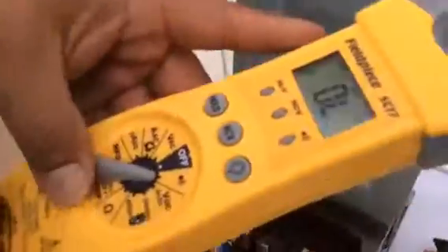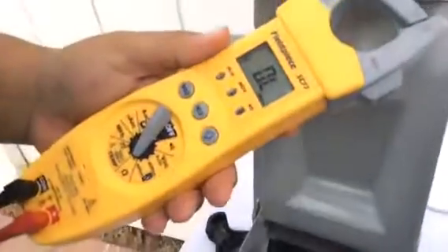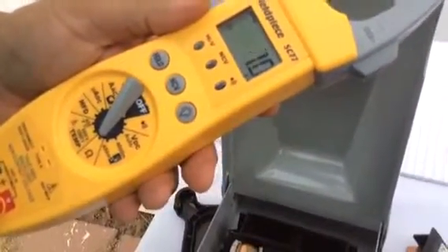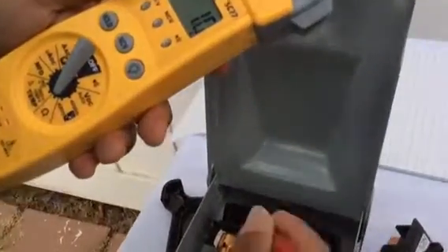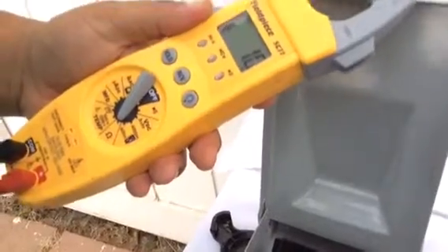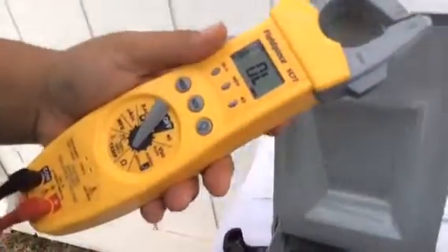We can also ohm the fuse out, check the resistance, and we have a resistance of around 1. You wouldn't want a high resistance because then it would become a load, with possible voltage drop.